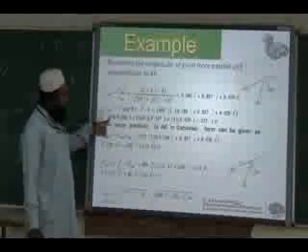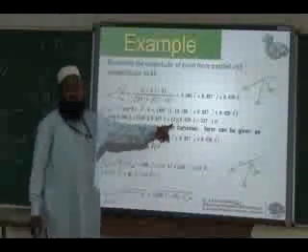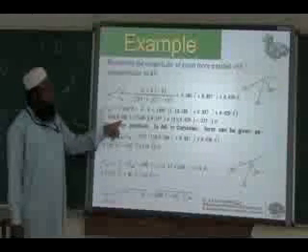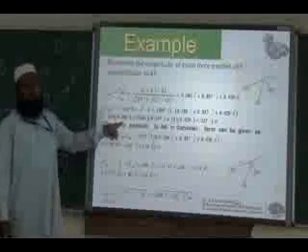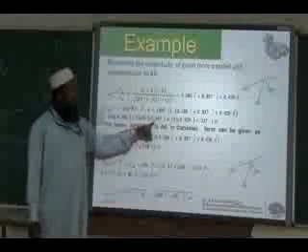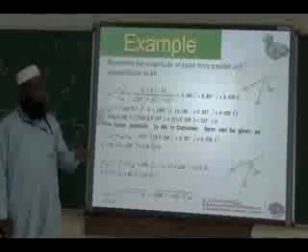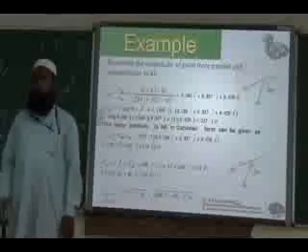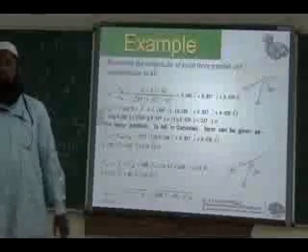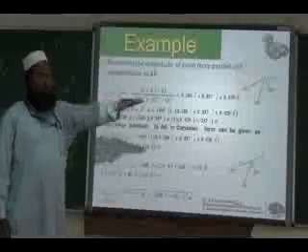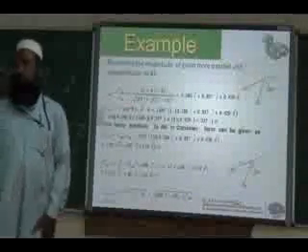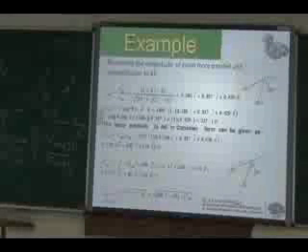Force F has got 0I and 0K, 300J. So force I component is multiplied by unit vector I component. Then force J component multiplied by unit vector J component. Like that. So the 0 in the first and last term refers to the 0 I and K components of force, because force is acting parallel to Y. So there is no I and K component for the given force, 300 Newton.